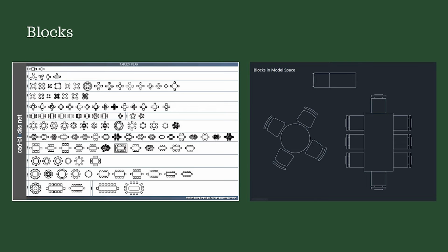Blocks are a group of lines bound together as one object and move as one piece. They have to be downloaded from the internet from a source compatible with AutoCAD and imported into the drawing. Much like the background image, the blocks had to be scaled to the proper size. Once imported, a few of the blocks are rotated using the rotate tool to adjust them all to the right orientation. Blocks give a sense of scale to the drawing because they are typically everyday objects that a person can relate to.